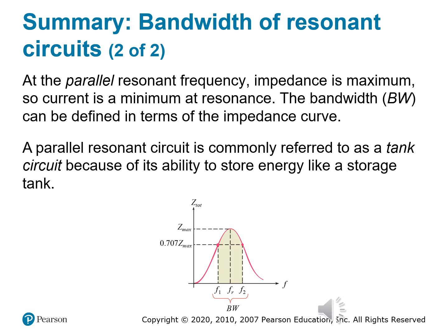And here's where things get interesting to electronic engineers at least. At parallel resonance, the circuit flips the script. So instead of current peaking, it drops to a minimum. Impedance, what about that? Well, it goes sky high. The circuit resists current flow at its resonant frequency, and it becomes what we call a tank circuit.